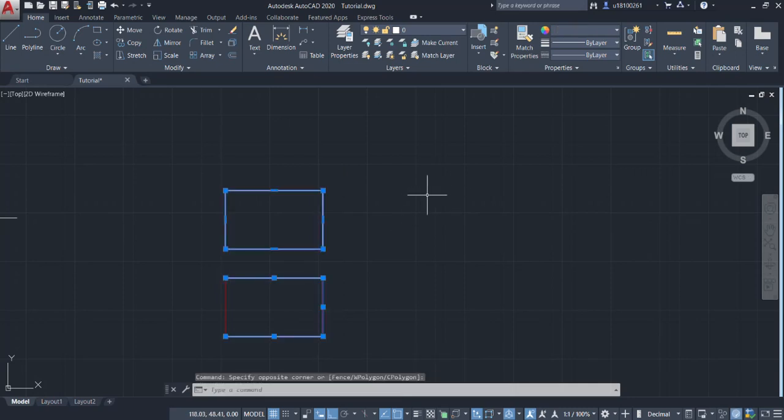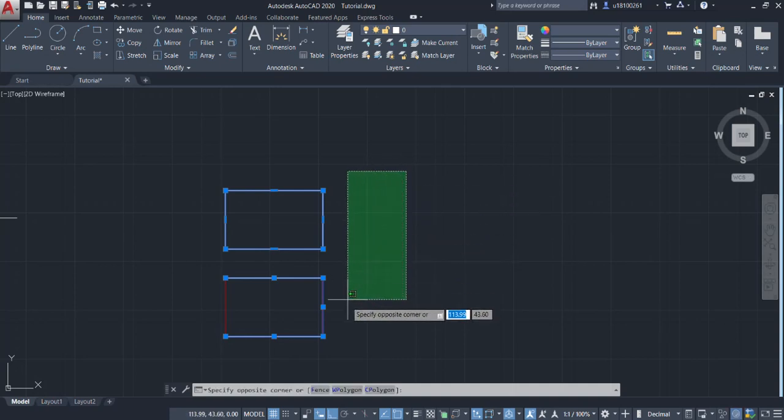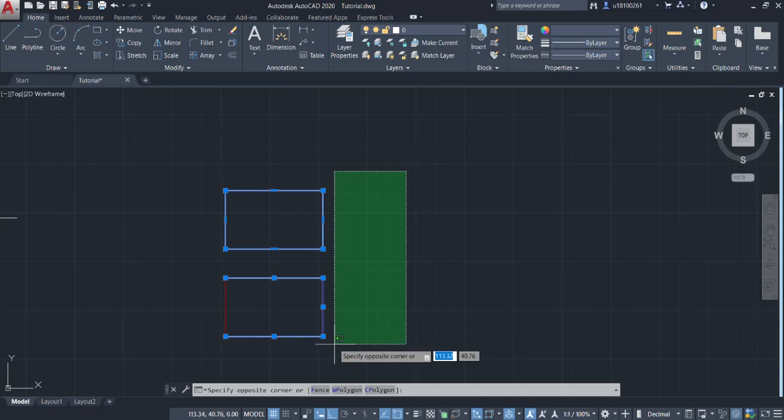If you press twice, as you see, it selects the whole polyline, since the polyline is one object. But with the original rectangle, drawn with the line option, it selects three sides of it. It does not select the far left side. This means that when you're selecting from right to left, it's going to include every segment, even if there's only a small piece of a segment within the select box.